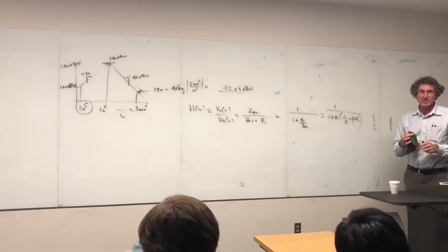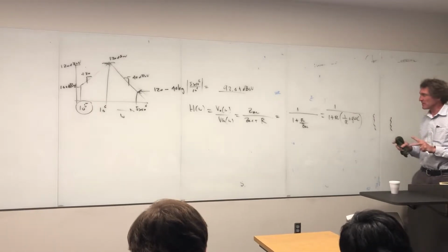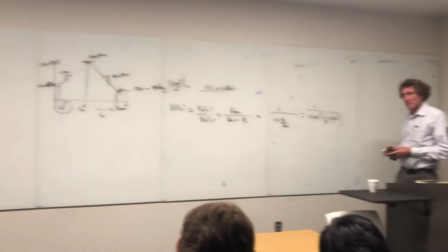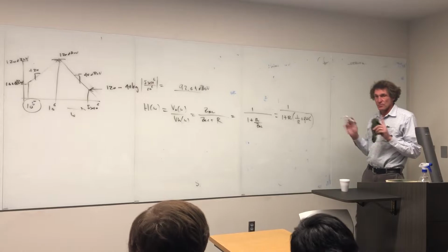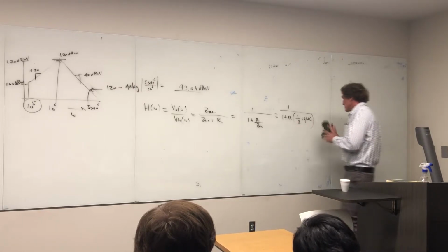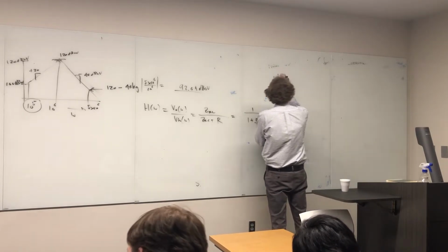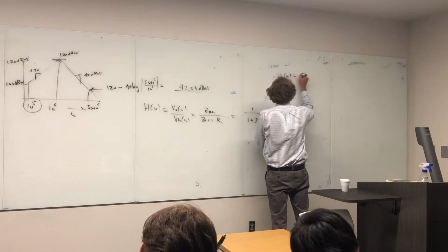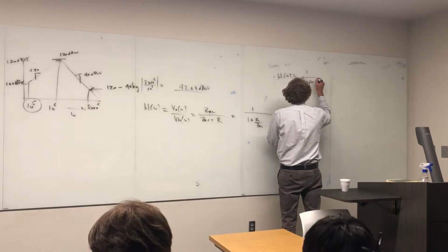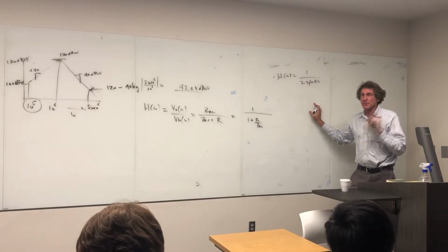You know, no matter how many times I go over this, I still know that people mess this up. It's routine. All right, now, can everybody see R times 1 over R is 1, right? And R times this just renders this whole thing to be, and I'll put it up higher, my H here is going to be 1 over 2 plus j omega R times C. Does everybody agree? There's a 2, not a 1.